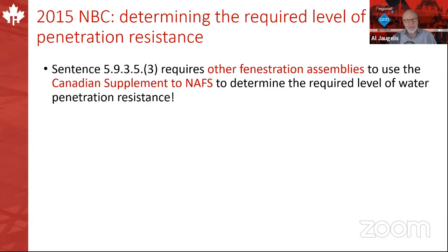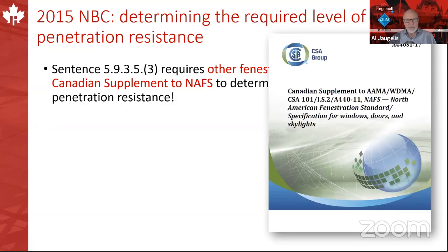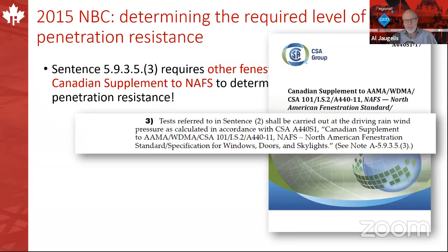So it's a requirement to use this Canadian supplement to NAFS. And it's good practice to have a copy of that standard. It's a good practice to understand it. Honestly, if people would actually read that standard, they'd learn a lot of very important information about the calculation of designed wind pressures and about the methodology that's used in the standard. And it has methods within it that you can do the calculations. But we know, practically speaking, a lot of people don't get around to that.